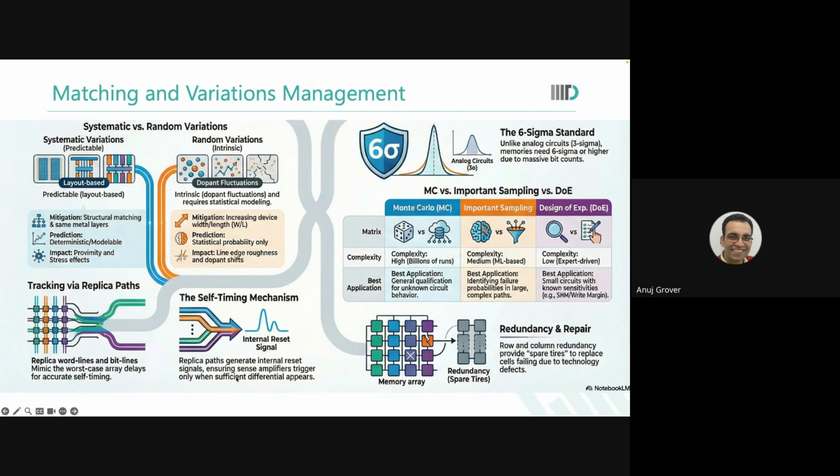So what we did was we had something going up and generating a signal which would trigger the bit line discharge. Then locally the replica word line would get generated. Again, as a designer, you have to play and ensure that all the pieces of the puzzle match.